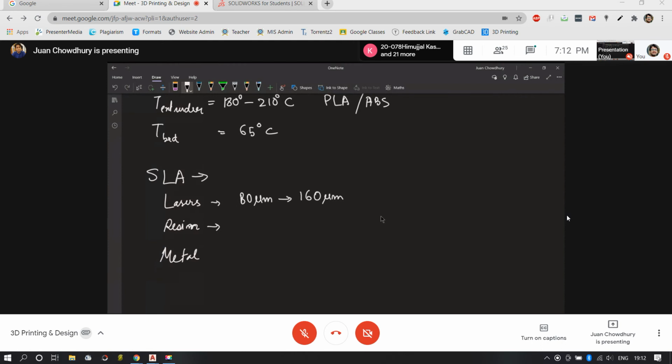Now, one thing we understand is that we need to control the lasers, of course, the intensity of it, and the switching on and switching off of the laser. Where exactly do you want to print? That is control parameter number one. The problem with SLA and SLS machines is that the raw material comes at high cost. Of course, you are going to get very good finish, but they also come at a really high cost, because the chemical equilibrium of the system has to be very homogeneous. I mean, homogeneous in the sense it cannot vary within the volume much. Otherwise, it will significantly affect your parts.